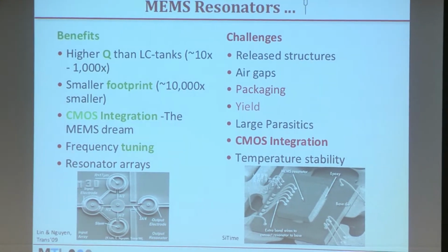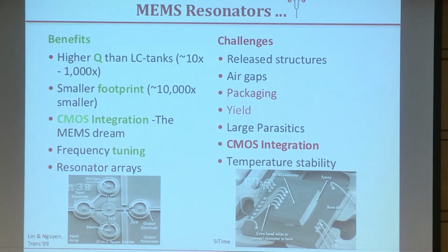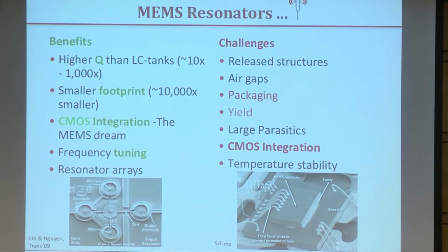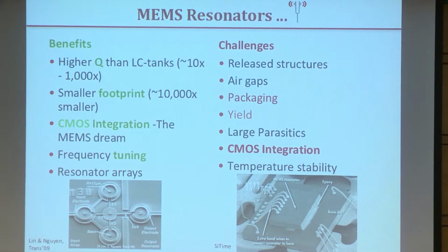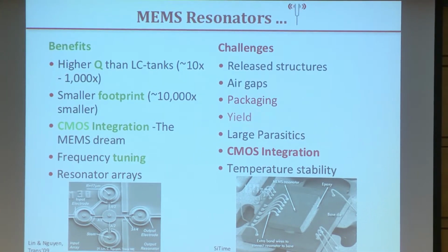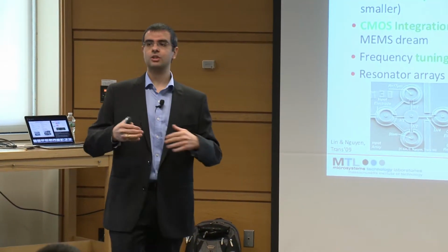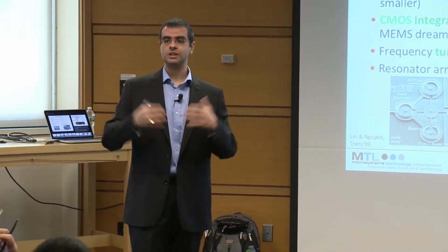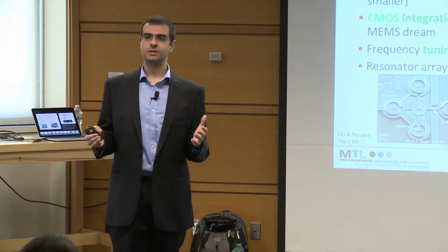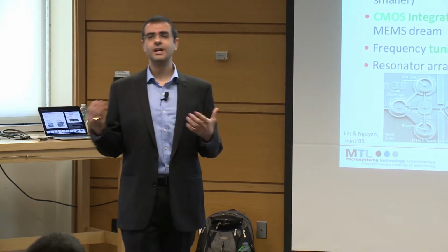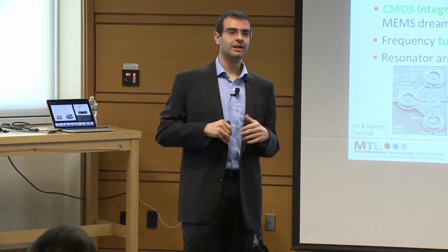We need to hermetically seal our MEMS resonator in order to protect it from all these environmental conditions. And let alone, these free surfaces also create some problems during processing. They might result in lower yield due to stiction and other problems. So what if we can just get rid of all of that, get rid of all these release operations and have a completely solid MEMS resonator? It doesn't make much sense to talk about something that vibrates while it's completely solid, but that's what we will